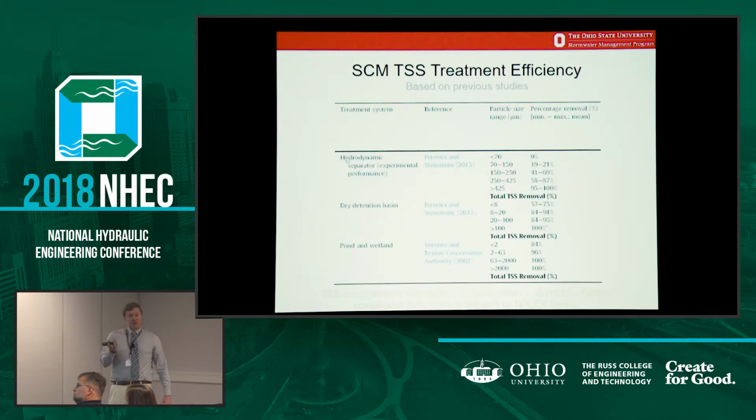One of the other things that we found that was interesting is the TSS concentrations coming off the roads were actually much smaller than what the last speaker talked about. The average concentration that we saw was 35 milligrams per liter. So it was very clean water.